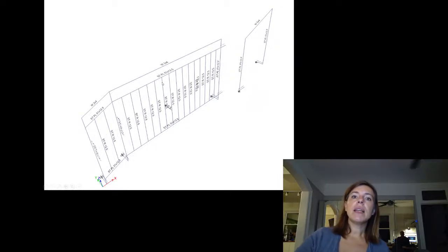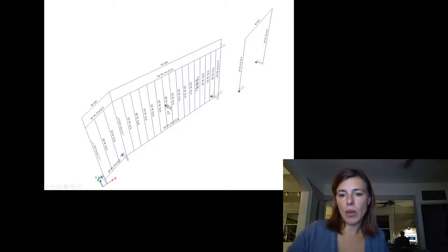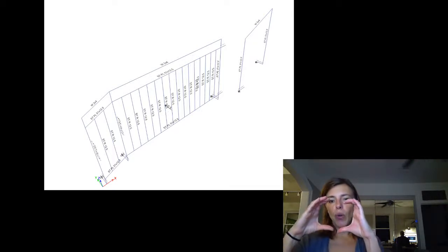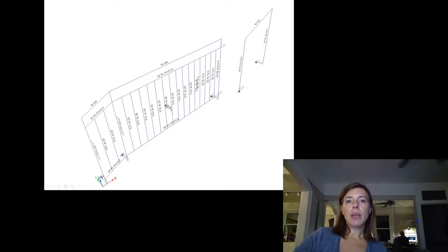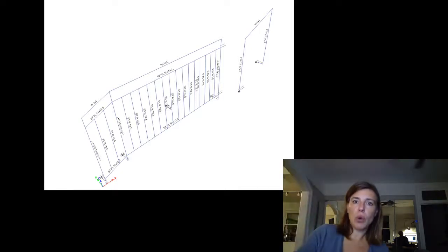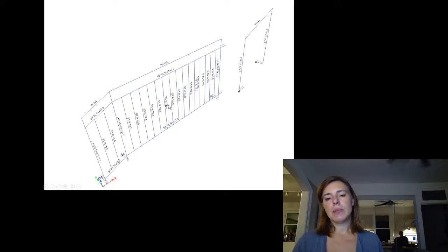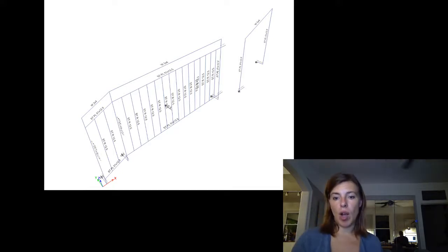And then here is my picket load with that 0.5 kilonewtons that the code specified. Now that can be over a 1 inch or a 4 inch by 4 inch area. I often apply it as the 0.5 to see where we land. Remember, this technically could be spread out over a 4 inch by 4 inch area, but that 4 inch by 4 inch area is still that one picket. So that 0.5 with a ball could push right on that one picket. So I want to really check all of the options on this.